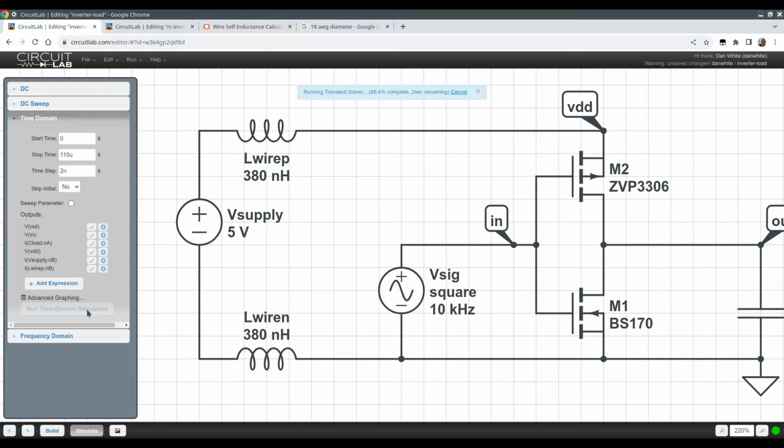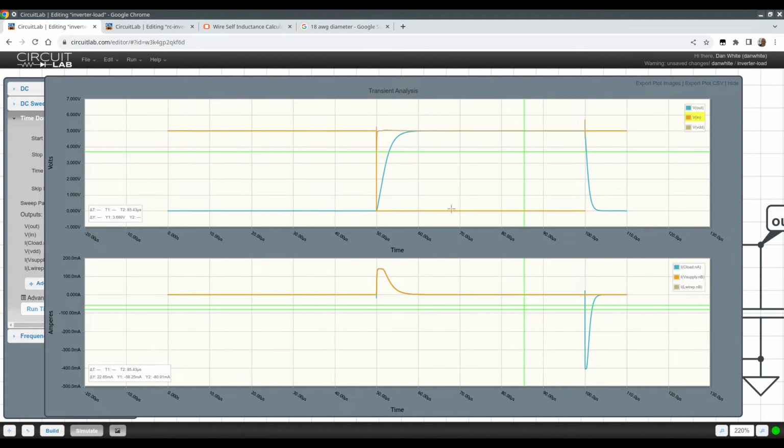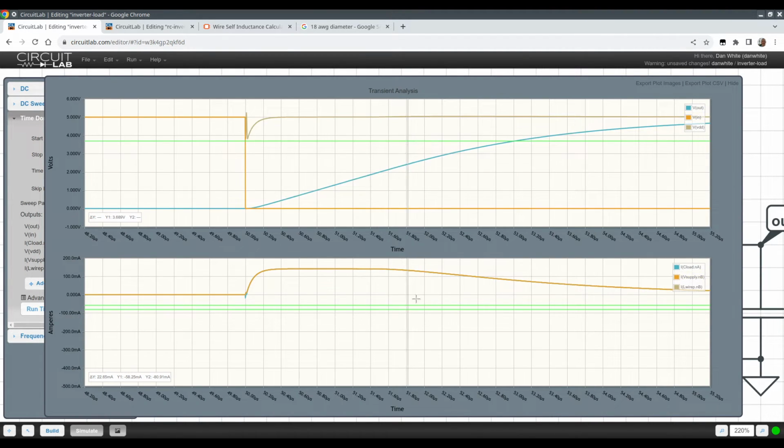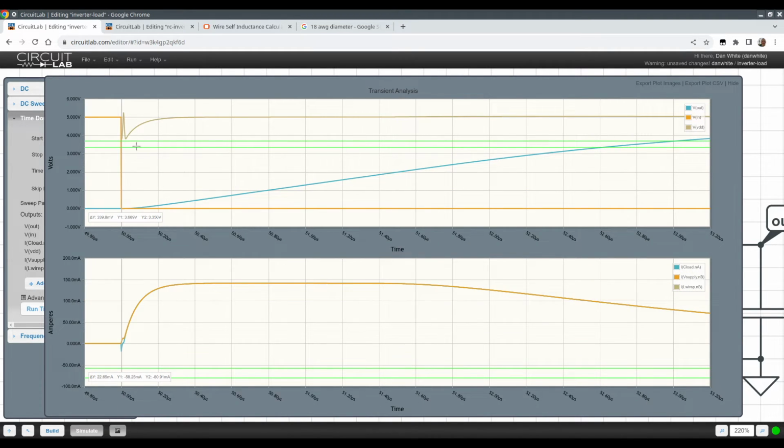We'll fix this just like we did in the lab by adding a capacitor between the power supplies at the point of the load. Okay, so we have extra glitchy stuff. This is a really high frequency ring, so we even need to simulate this more data points right here. LT Spice will automatically add more data points. Great.